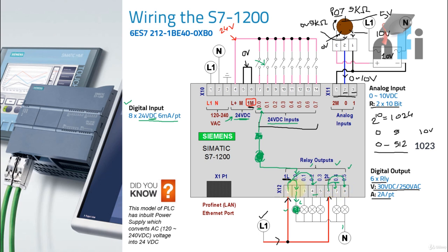So this one common has 4 output contacts, this common has 2 contacts. So you can also have 4 AC outputs and 2 DC outputs by providing DC here. It's not always necessary to short 1 and 6. If you have 2 DC outputs, you can connect DC to number 6 and AC to number 1. That's how you can change the inputs and outputs.